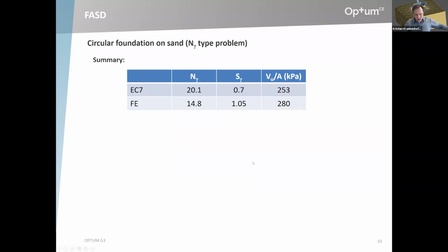But then there are people who say that actually, when it comes to the bearing capacity equation, we have made a mistake already. They say that N gamma should be calculated on the basis of the plane strain friction angle. I just mentioned a generic friction angle of 30 degrees. I didn't say whether that's plane strain or triaxial or whatever. So we should be aware of what angle we're using, and when calculating N gamma, we should use the plane strain angle. The idea, of course, being that the bearing capacity, like pretty much everything else in geotechnics, was developed with reference to plane strain. So it makes sense to use the plane strain angle.